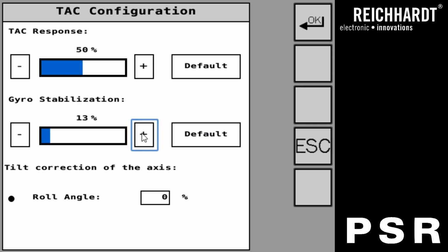And you can adjust that by hitting plus or minus. You see it'll stop up at 40. Since we're steering a combine, we're going to leave this at 0. If you have an older solution that has an LT controller, silver box, and a gyro, or would require an external gyro but no gyros installed, this would not be applicable. You would need to make sure that this was left at 0 or you'll have a gyro error code. It'll be looking for a reading from a sensor that doesn't exist.